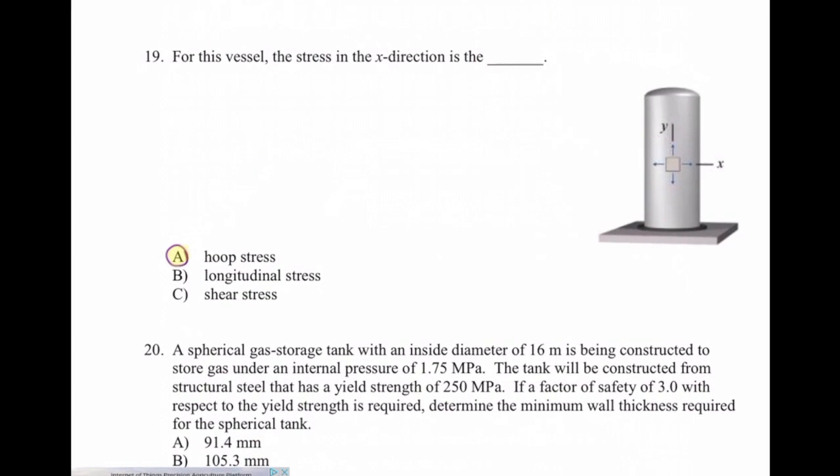Question 19 is another conceptual question. For this vessel, the stress in the x direction is hoop stress, longitudinal stress, shear stress. So this question actually competes with that question that we just talked about. Stress in the x direction is hoop, because that is circumferential in that.